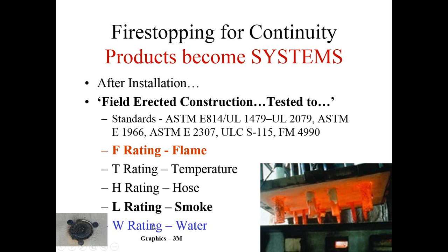rating. The W rating is relatively new. It's maybe 6, 7 years old. We've asked UL to improve it because basically what they do is pile water on top of the penetrating item or on a joint by putting another plexiglass pipe around this penetrating item. That plexiglass pipe is then filled with 3 feet of water to simulate a 3-foot head of water. If in 72 hours there's no leak down below, guess what? You've got a W rating.